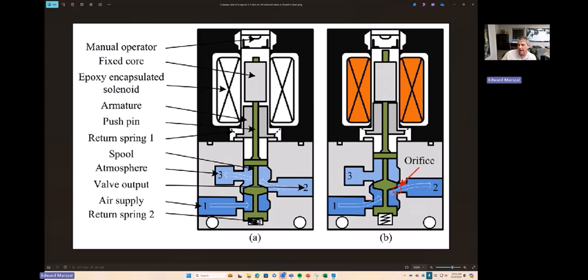So you need to think about how this can fail, so you go through every component and say, well, what are the failure modes of that component? So let's talk about a couple of failure modes. The primary failure mode for a solenoid is coil burnout. You see a big red X here, but you're basically talking about hundreds or thousands of loops of copper wire. And when electricity flows through all those loops, it creates magnetism.